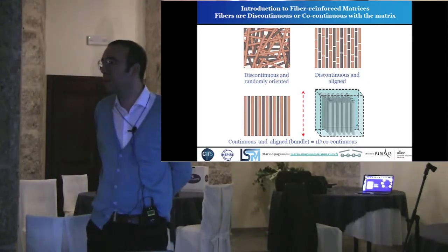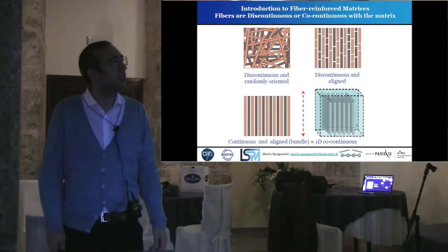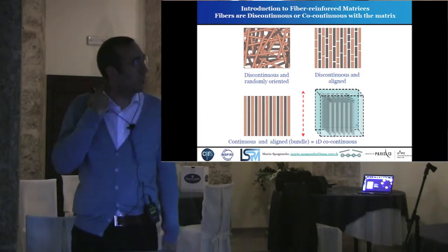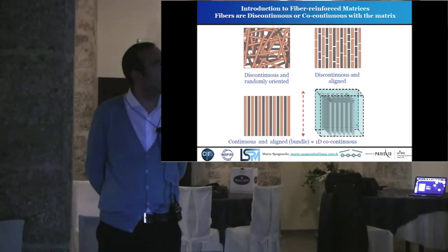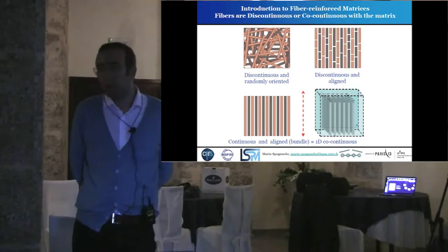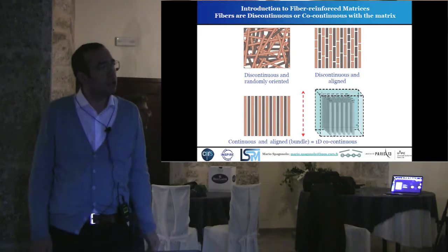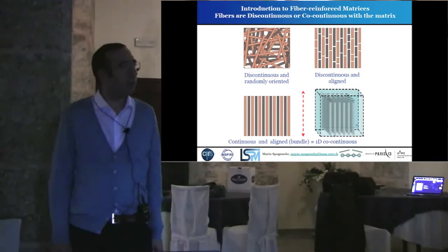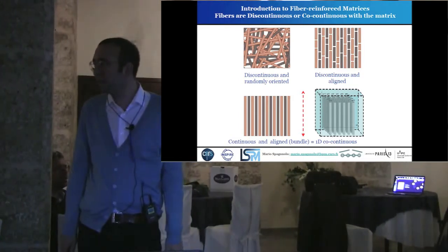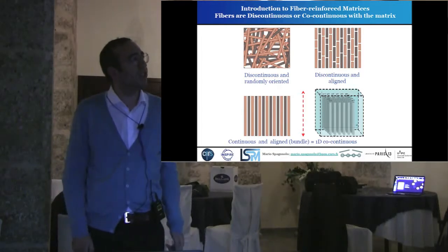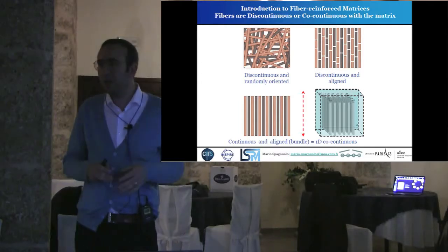fiber reinforced materials, and so we have some possibilities. We consider we can have continuous and randomly oriented fibers. We can have the alignment, and also continuous and aligned, so a bundle. I will speak about a bundle, a fiber bundle contained in a soft matrix, and the aim of this work is to start from the moduli of the single